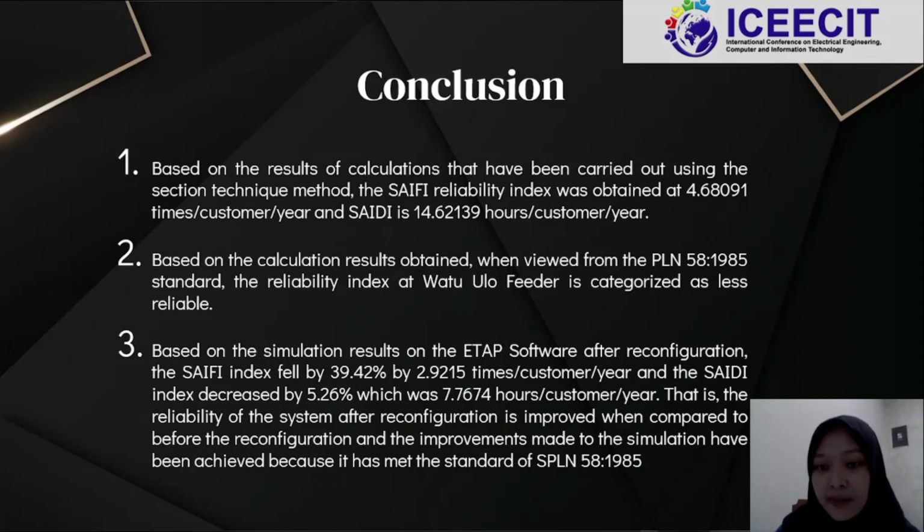And the last, or the third conclusion, based on the simulation result on the ETAP software after reconfiguration, the SAIFI index fell by 39.42%, to 2.9215 times per customer per year. And the SAIDI index decreased by 5.26%, which is 7.7674 hours per customer per year.